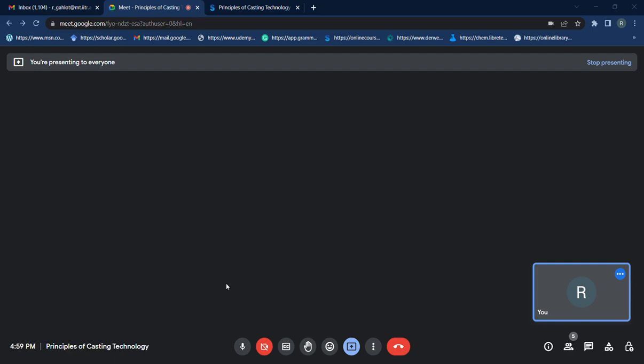One more question comes from this. Can you differentiate between blowholes and pinholes? Blowholes are due to air entrapment, and pinholes are due to hydrogen coming out. Generally pinholes are due to hydrogen, while blowholes can be due to any type of gas or any other entrapment of gas.